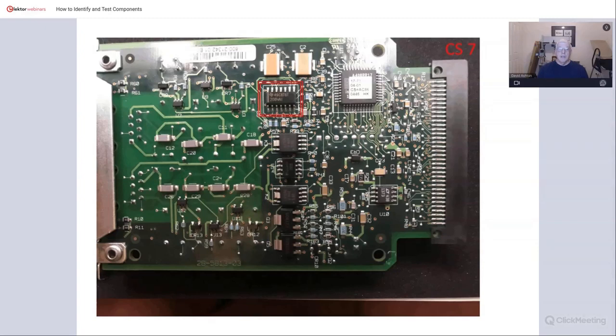In this case, you go to the Texas Instruments website, stick 2064 into the search box, and up pops a data sheet for the TLE2064A. A lot of you will be familiar with the TL064. It's a quad operational amplifier, JFET input, and that's what this is. It's an enhanced version of that with very good specs. Yeah. Next slide, Clemens.